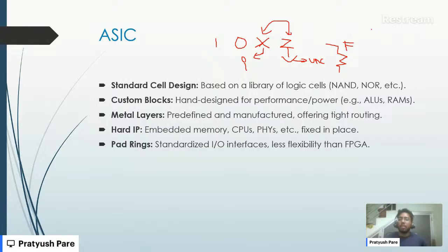But if you come down to a very low, very deep level, then you would see that for a floating net, let's say I have a floating net here and a wire here, then due to some coupling capacitances and resistances, this net can charge or discharge to some value, but that is a very rare case. Got it?